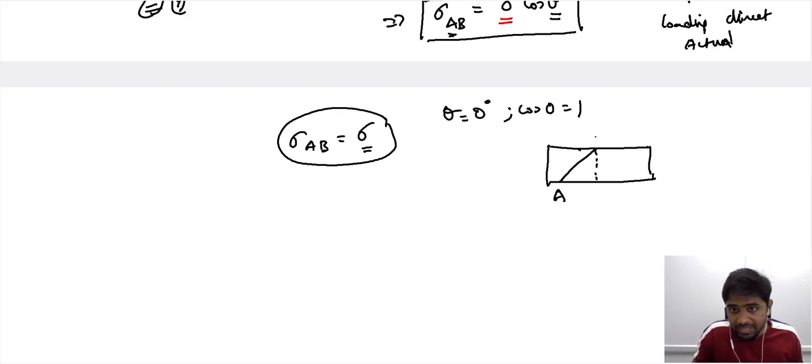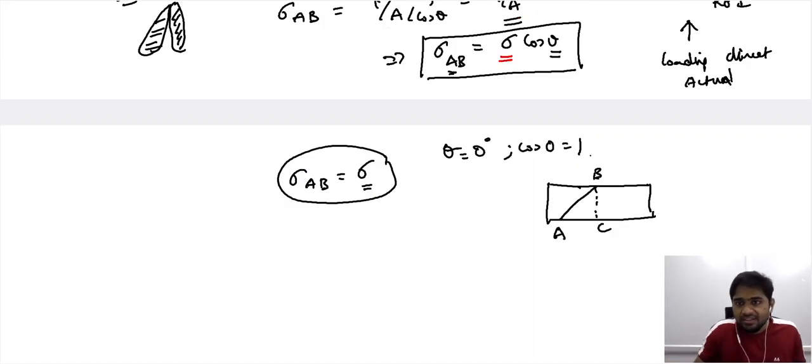So we refer to this as A, B and C, and we have been discussing this part. Now this expression tells us that when the loading direction is in this way, the stress experienced by AB is a portion of what BC experiences. And so what we have is the resistance offered by AB along this direction. It can be quantified in this expression here. So the stress can be referred to as the resistance offered by the cross-sectional area, and that resistance is along this direction here.